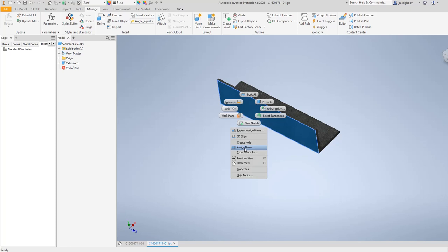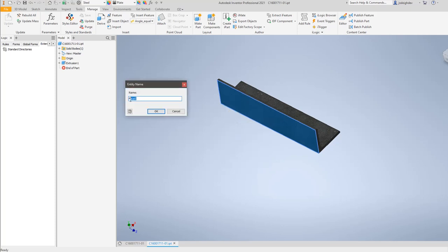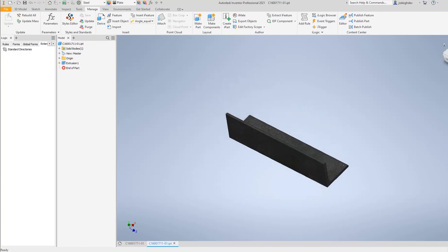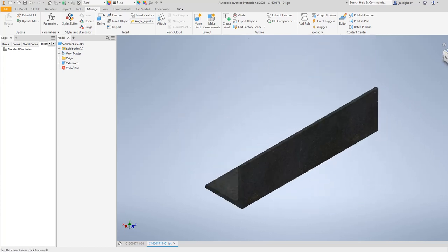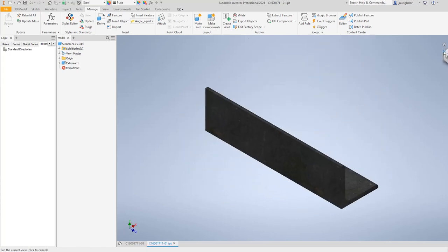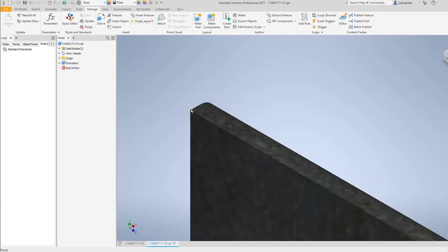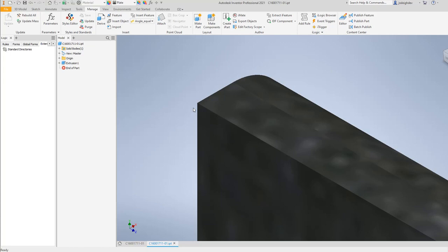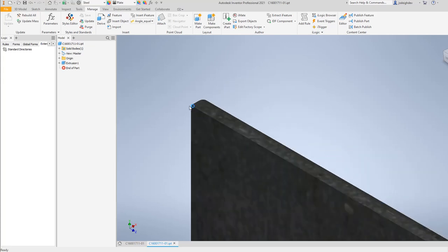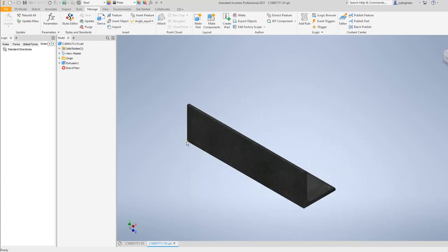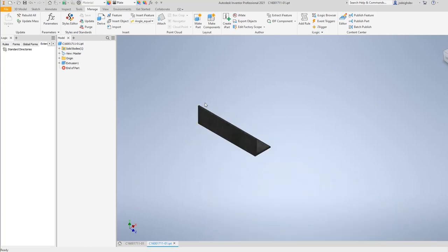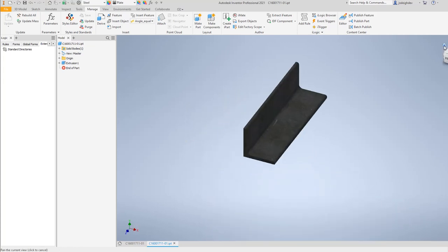Now the general problem is that every single face had to be named for you to dimension something, so that made your code so tied to your models, it was hard to have generic dimensions. So your productivity of actually automating drawings just went really low. The other way had the same issue, is you put work points everywhere you wanted to make a dimension, and then you created proxies to those work points. That had the same issues. You had to have all these work points in your model. So it made it so tied.